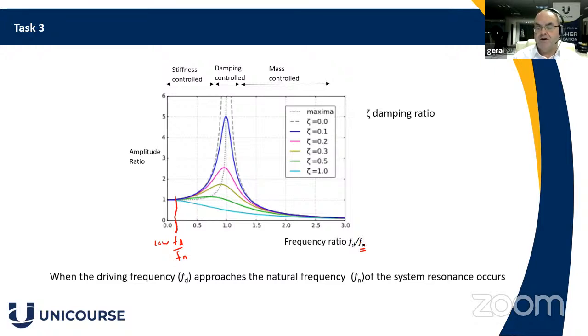I used to work in the shipyard, and one of the examples was that you had some vibration in deck panels, which just happened to have a natural frequency that coincided with one of the disturbing frequencies in the main engine. So what was done to stop that resonance in those deck panels is that you just weld a bracket on, and that changes the stiffness, and changes the mass as well. So you change the natural frequencies so they don't coincide.